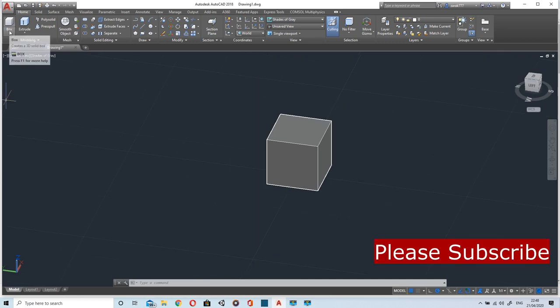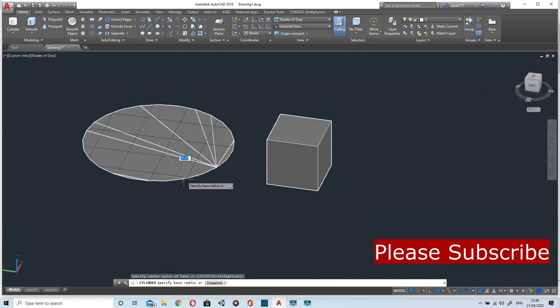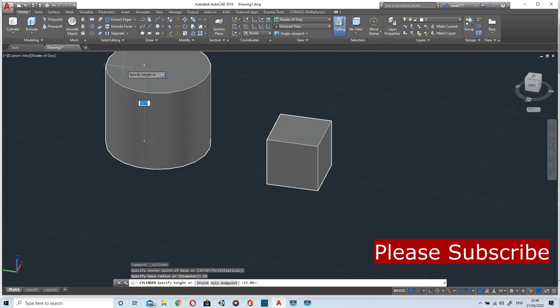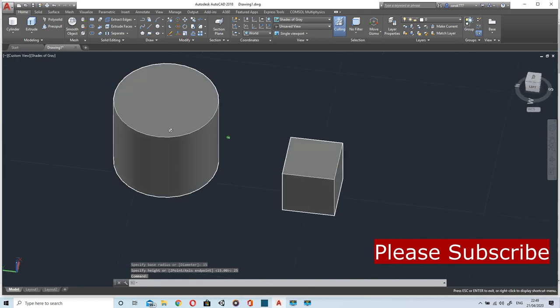Now let's move to another solid object, that is the cylinder. For the cylinder, it is asking me the center point of the base of the cylinder. So I'll just click randomly. Then I will put the radius as 15 and the height of my own required height, that is 25. So this is how you draw a cylinder. If you want to draw a cylinder, this is the easy way.